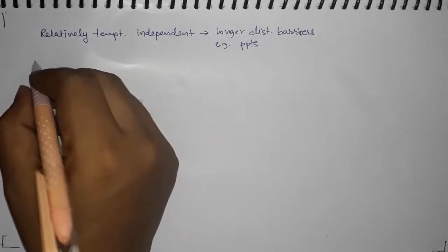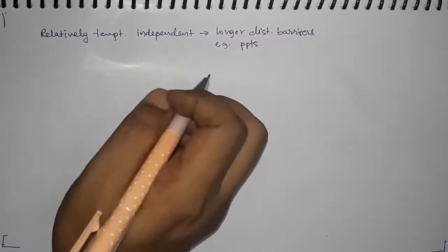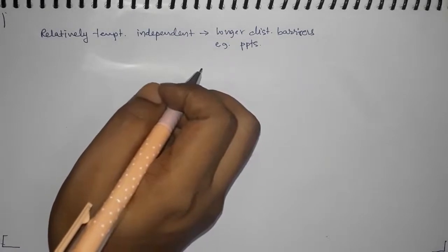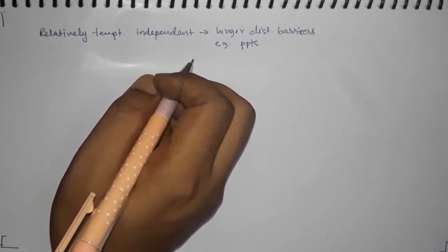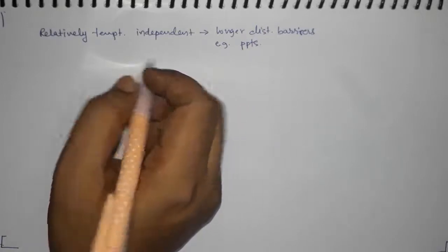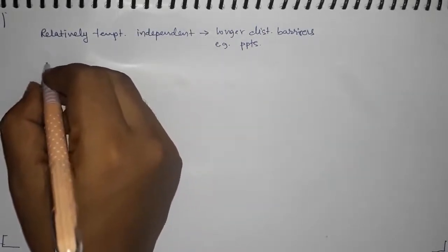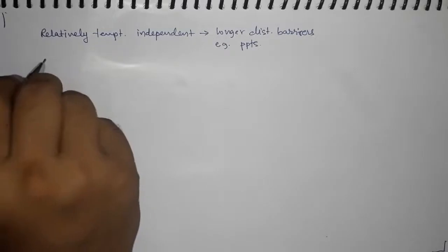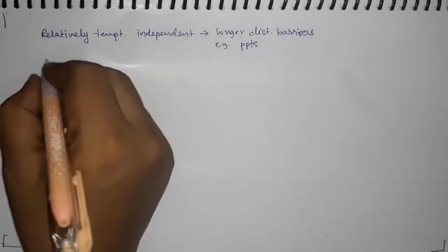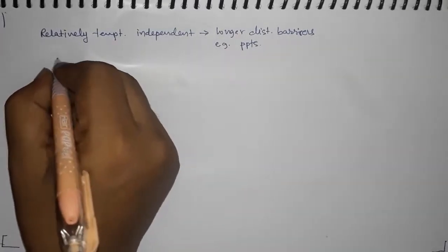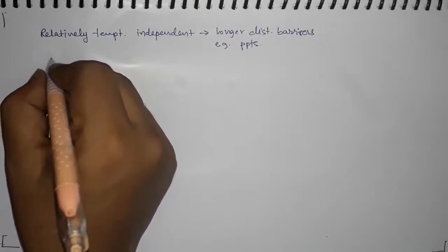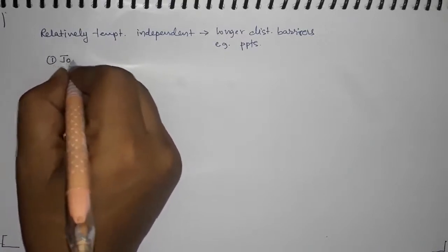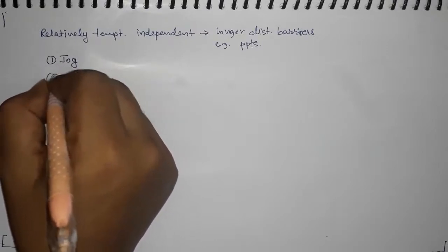Okay, and now we will discuss how dislocations can block each other. We discussed about Lomer-Cottrell, but dislocations can intersect with each other and block each other also. So when two dislocations intersect with each other, they can create two types of entities. One is called a jog and another is called kink.